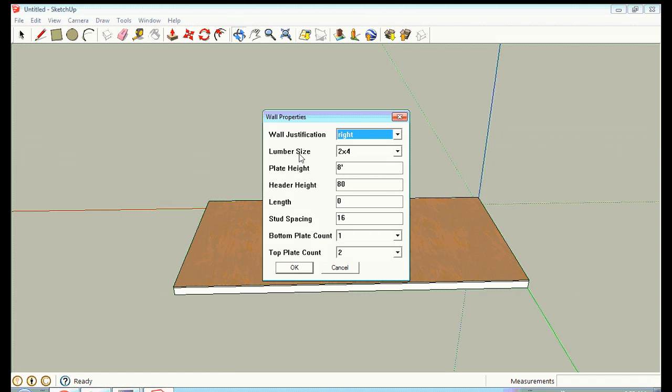We're going to choose a lumber size of 2x4 for the walls. Now, if you're in a very cold climate, you may want to go with 2x6s. You can put more insulation into 2x6s, but because these structures are small, used for houses, and are going to be heated, they're going to have enough insulation in the walls. We usually use 2x6s for the roof and the floor for a house structure, 2x4s for the walls, but if you want to go with 2x6s, or you could even go with 2x8s if you want, but 2x4s are enough structure and will support the weight of most snow loads in most areas for a small structure like this.